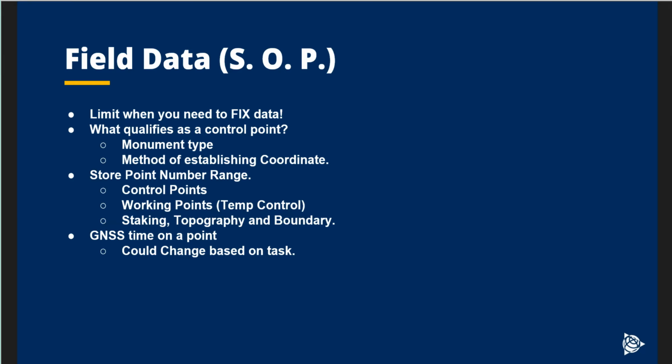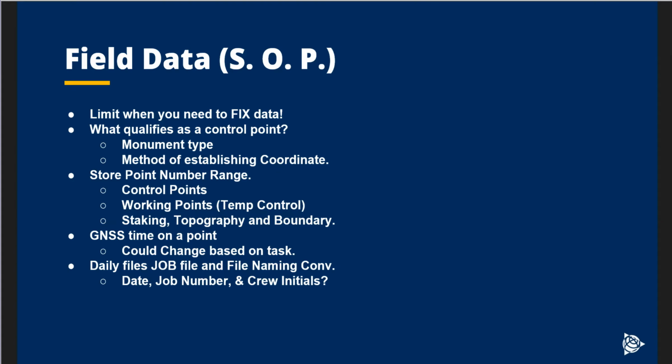And then, really important, time on point. If you're using RTK, time on point is what makes a big difference, right? I've seen so many cases where people are taking a 1 epoch shot or a 2 epoch shot. What's the difference on a 5, how much time does it really cost you to up those epochs a few? Trust me, time is your friend when it comes to RTK. Giving that little more redundancy, allowing the covariance matrix to establish what's really going on there, will save you a lot of time.